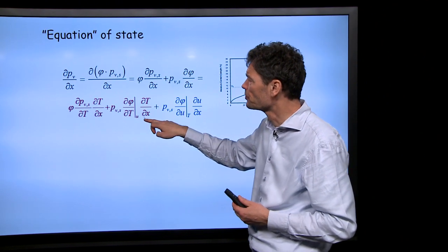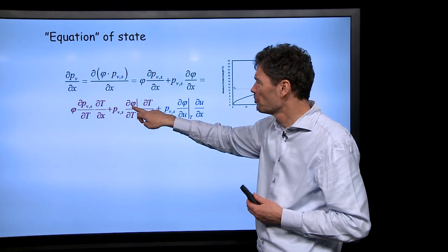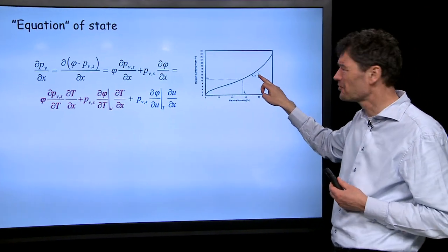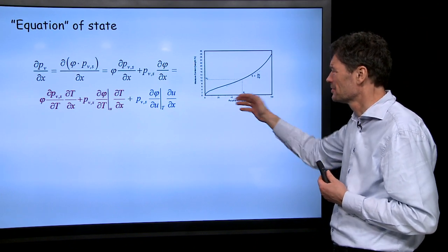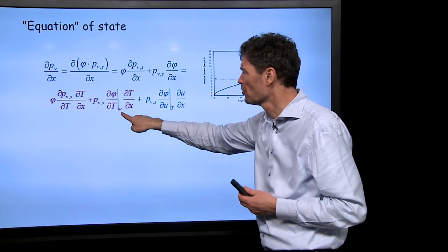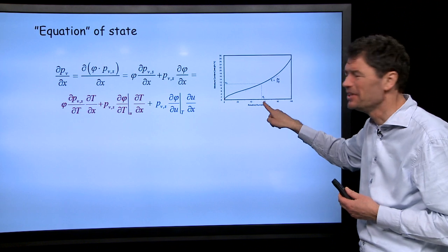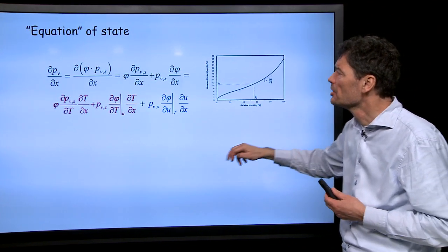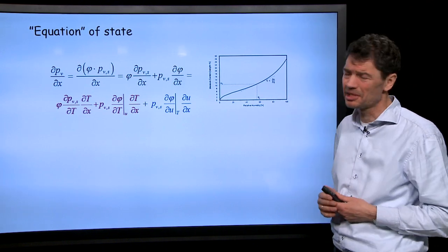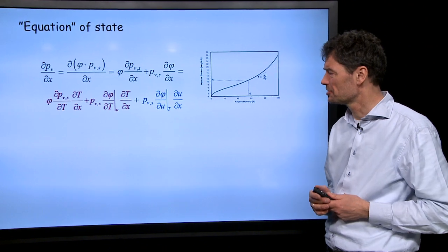Also, there is a small effect, I should say, but it's there in principle, whereby the absorption curve, we sometimes call it absorption isotherm, at different temperatures has slightly different positions. So for a specific moisture content, at a different temperature, there would be a different equilibrium phi, relative humidity. So there is a small effect here also about how the curve is temperature dependent. That should also be considered as a secondary issue.